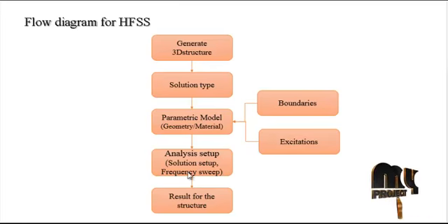Next we set up the analysis. In this analysis setup, we give the start and stop frequency and the center frequency, for example 3.5 GHz. Finally, we calculate the results like return loss, VSWR and bandwidth of the antenna.